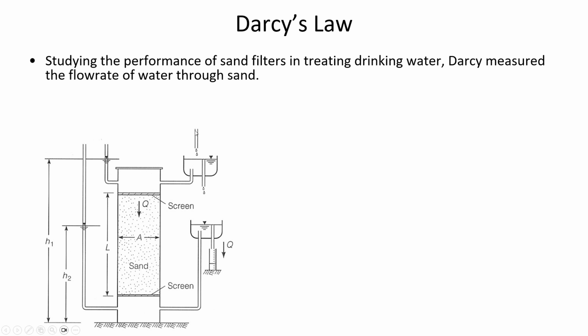What this is showing is that we have a constant head, both for the water coming into the soil column and the water going out. So that means we're in equilibrium with the flow rate that's going through here, and it's equilibrium in terms of the head values. There's a certain amount of water pressure for the water that's in the soil, and a different water pressure at the bottom of the column or at the end of it, if you think about the water traveling in a certain direction from the top of the column to the bottom of the column.